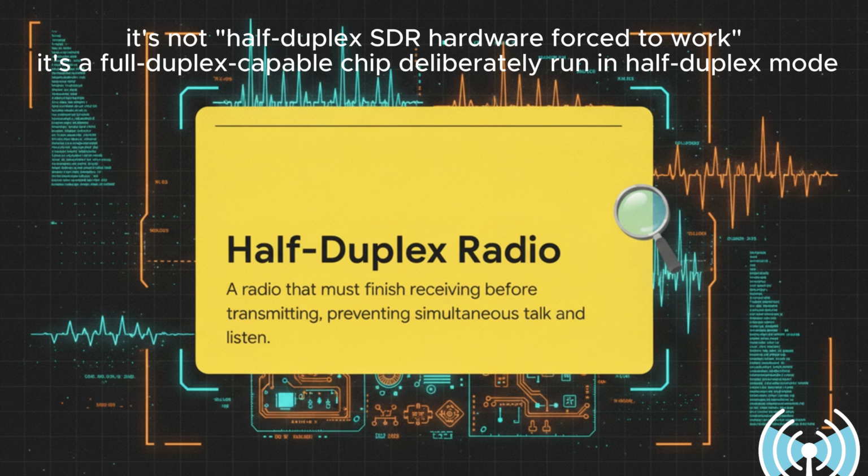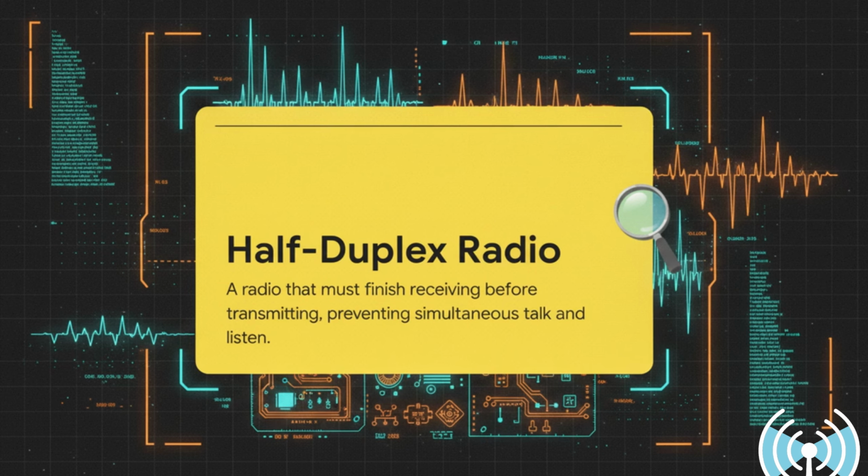Because of this, every single extra redundant copy of a packet chews up shared, highly contested RF airtime that every other node desperately needs. Compound this with unseen, overlapping nodes transmitting at the exact same time, which we call the hidden node problem, and your signal collisions just absolutely skyrocket.